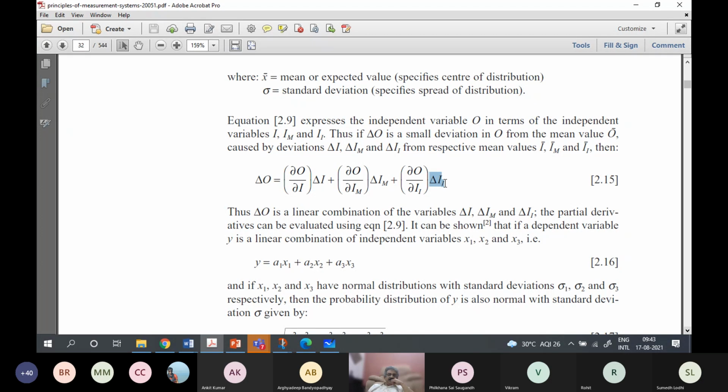On the other hand, if you go to a goldsmith shop, the weight of the gold is so precious. Firstly, the scale is going to be within a box, because if it is kept open, then a running fan can create some thrust on the pan on which the gold will be placed and can actually create an error. So the fan speed now becomes an interfering input, right? But we are not measuring the fan speed.